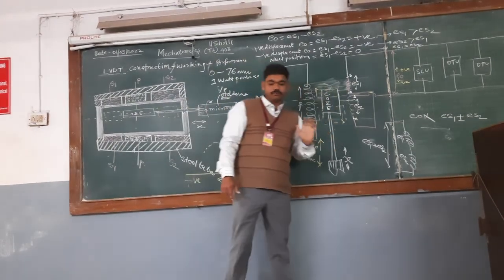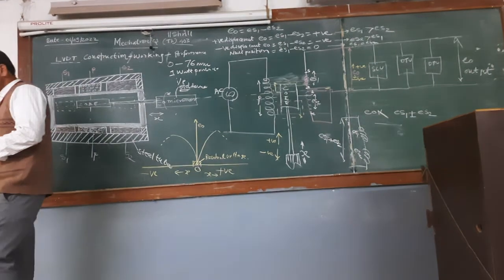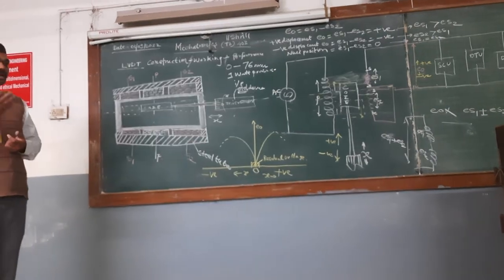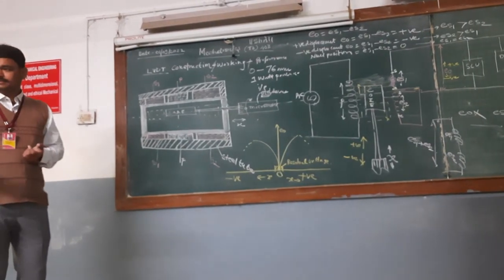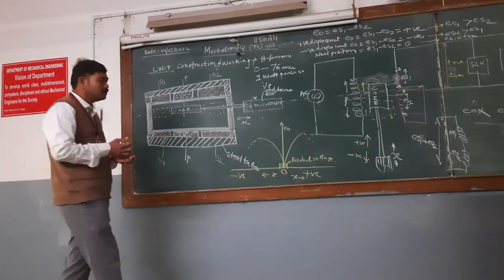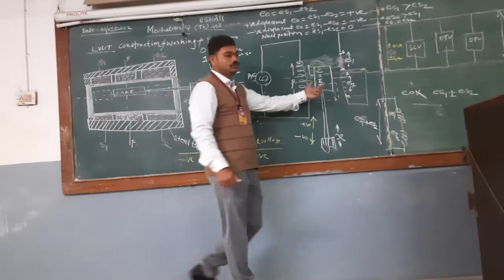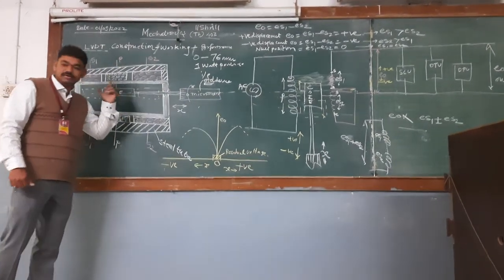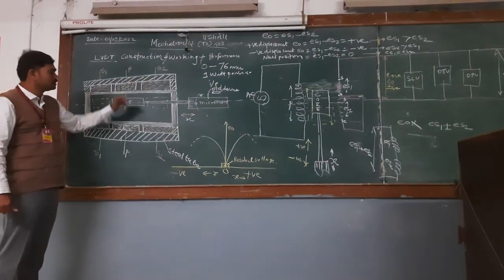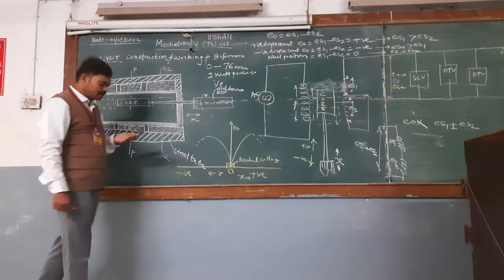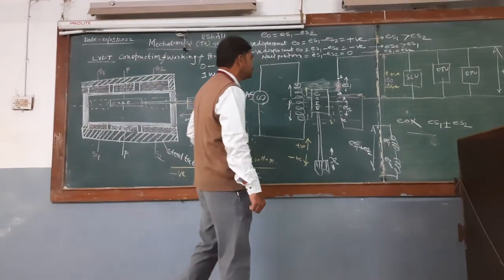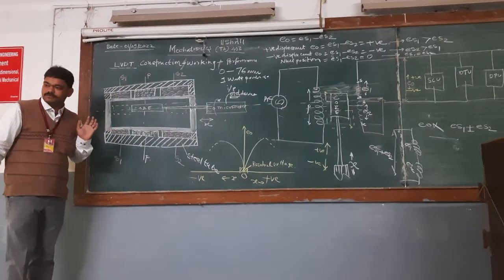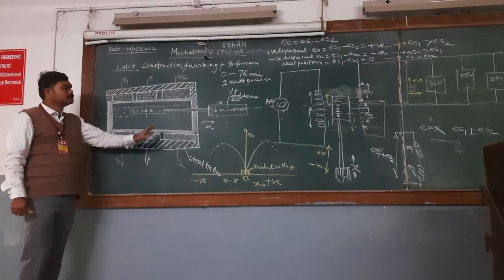So it is a very sensitive instrument to measure displacement in the proper way, where CNCs are there, or where very accurate and precise manufacturing is needed in the mechanical industry. In those cases, or in different gauges also, LVDTs are used. There are 1,000 applications for the LVDT. It has the advantage of rugged construction, as it is mounted in a steel tube. It will protect from damage, that means cracks, etc. There are certain limitations and disadvantages also. Okay, that is about the LVDT.